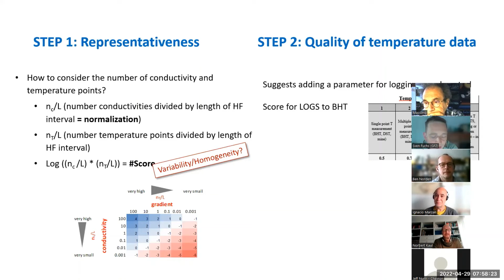But our group has used it in the past. And if I recall correctly, the accuracy of the determination was better than 0.1 degrees C. So it's 2 orders of magnitude less than the high precision temperature logs, but even 0.1 degrees C with a larger interval is quite good. And a continuous profile here means the resolution of the DTS is probably 0.5 meter or so, or even a bit less, probably a meter. It depends a bit on the cable you use.